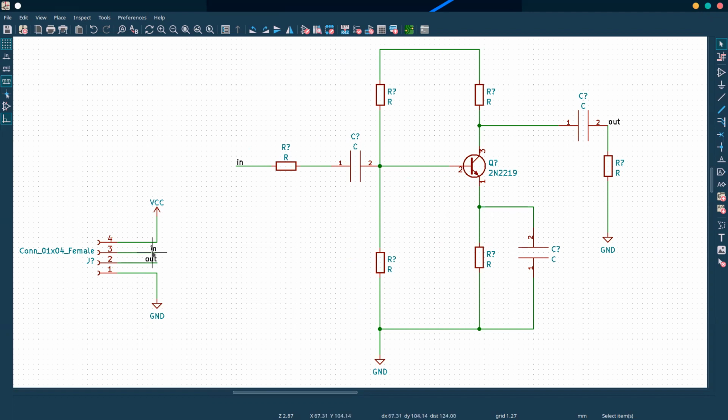Yeah, so these labels, this in is connected to this in. Oh, that's just the way labels work. Okay, and it's just a regular label. Yeah, so you add a net label, they're called. It's this guy, press L. And then the same name, yeah. If you have other things and you label it, they'll all be connected together. And you'll see why that's important when you lay out the PCB, because you click on things and it highlights what it is connected to.